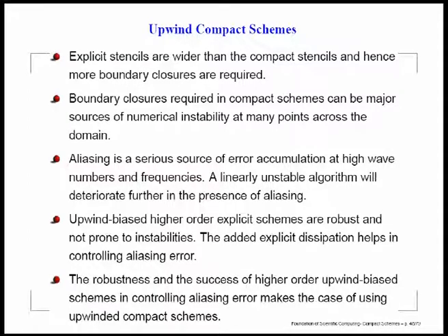Suppose I do first order upwinding, what is the equivalent dissipation term we have? It is a second derivative term. If I am taking a third order upwind scheme, then what will happen? I am equivalently adding a fourth derivative term. So all those even derivative terms add, explicitly or implicitly, those dissipation terms. And if you have those dissipation terms, what does it do? Of course, it attenuates.